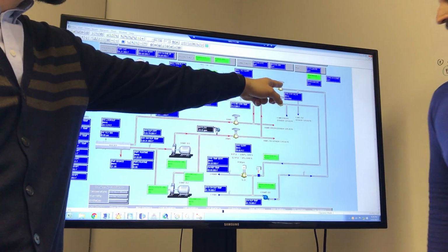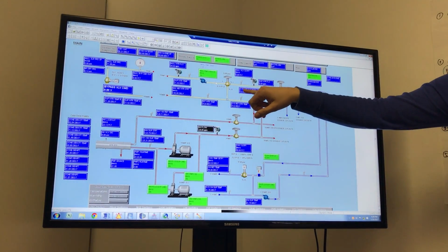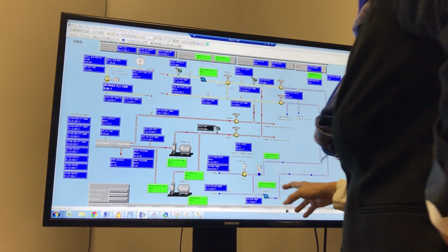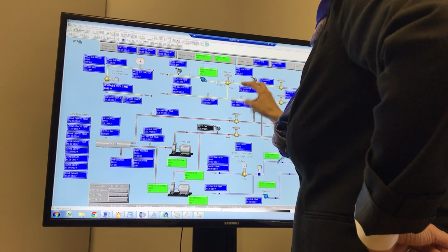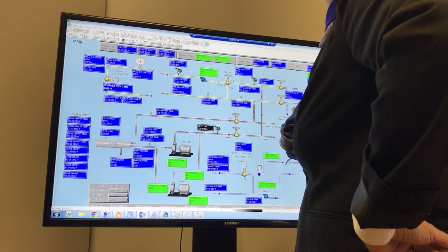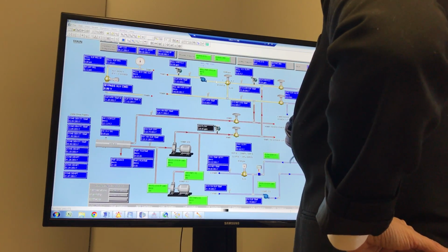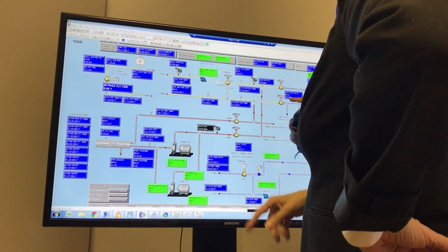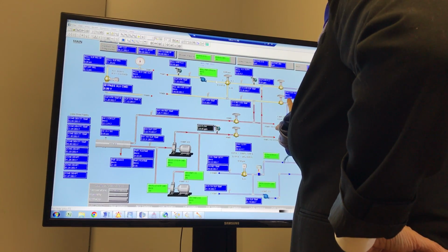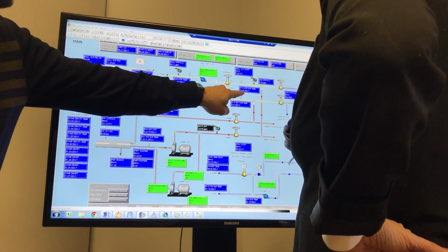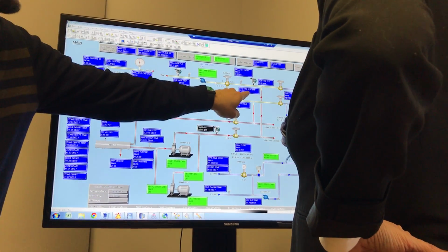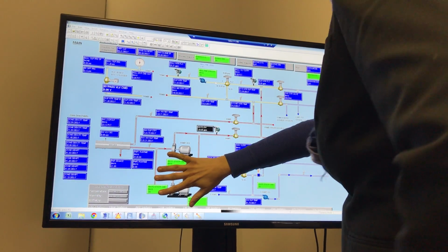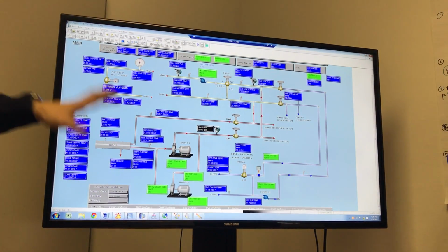How to prevent this is just using the valves, and checking what your incoming temperature is. So I'm still trying to guess, I can see obviously the blue flow and the red flow. So just to be sure that the cooling system is on in our floor, where will I see? This will go in cooling. I will check this temperature because it's 41, very cold. Then this will decrease if the cooling is off. If you don't need heating, it will just turn off. Green means active and on.